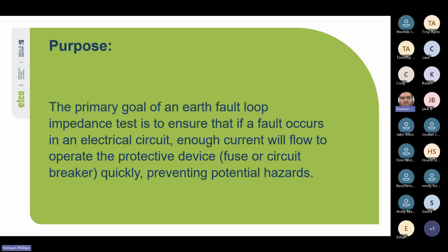We can measure it with resistance, and there are values for that, just base resistance, but we can't take into account what condition the transformer's in, how big the transformer is, or whether it's operating correctly. Because sometimes transformers just half fail, or not even fully fail.